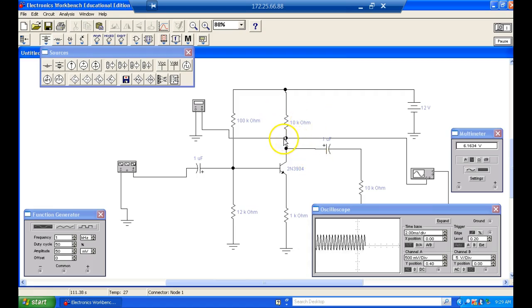So this is what we're trying to do. We're trying to get this AC signal through here. It wouldn't be any good to have an amplifier that does not do this. So what we're going to do is open this 100K. What should we expect to happen? How can current go up? Base voltage is going to go to what? It's going to go to 0, because we've lost the resistor that's connected to the power supply. So I've lost my power supply on the base.